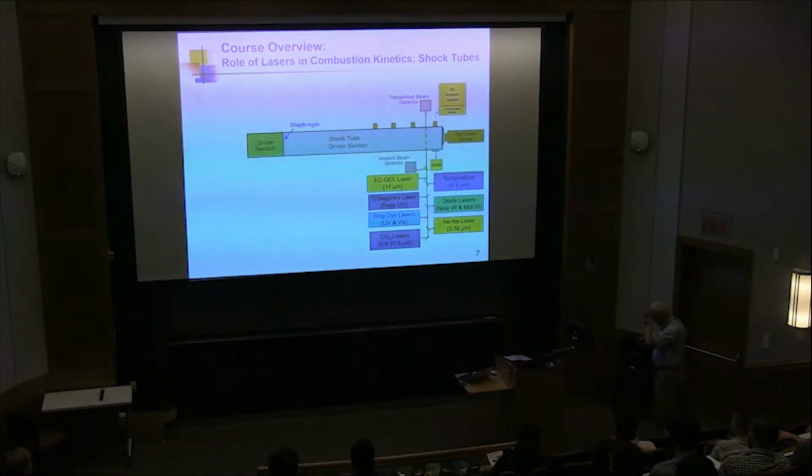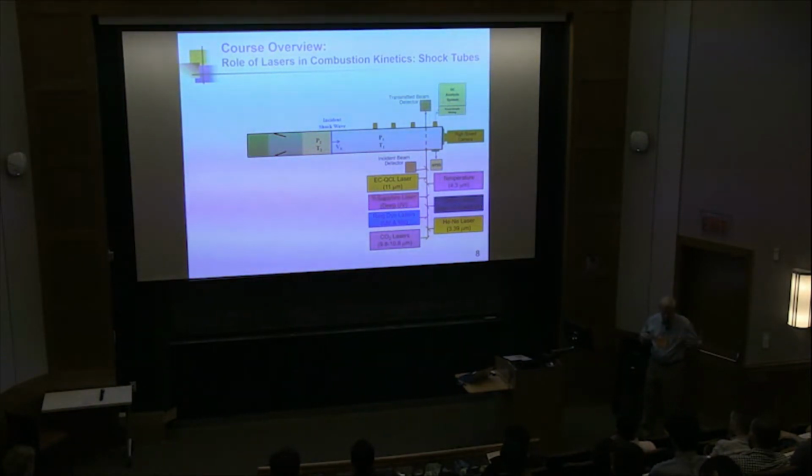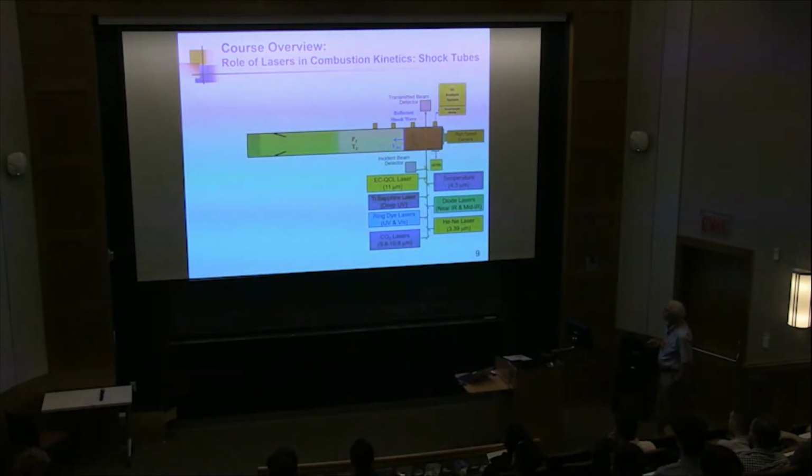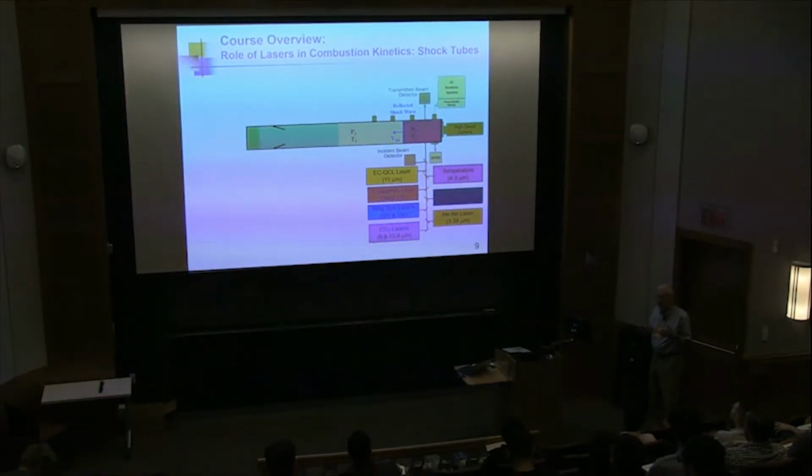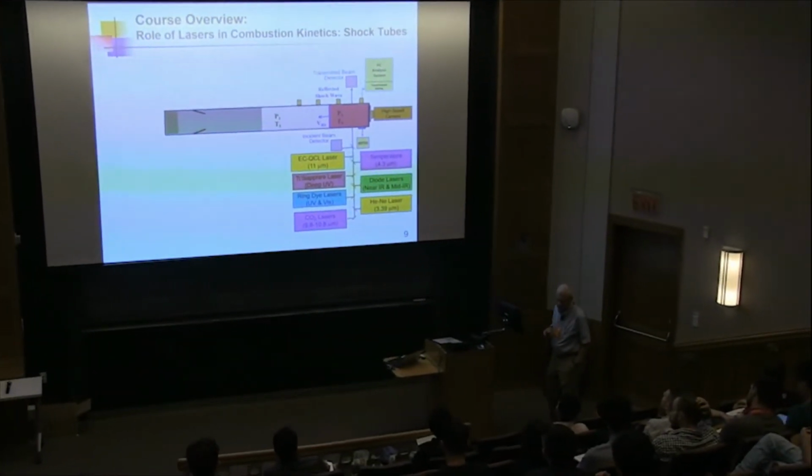All right, so how do we study this problem? We make use of a shock tube. There's a constant diameter pipe separated into a high pressure driver and a low pressure driven section. We break the diaphragm. A shock wave propagates down at some speed that we measure. And from that and the gas dynamics relationships that you've probably all had, compressible gas dynamics, if you measure the speed of the wave or its Mach number, you can calculate the jump conditions, and you can calculate region 2 behind that wave. That wave propagates down and hits the end wall and reflects, and the boundary condition is that the gas is stagnant. So behind that wave, the gas is nominally stagnant. So it's a sample sitting there for up to maybe 100 milliseconds, often only 1 millisecond.